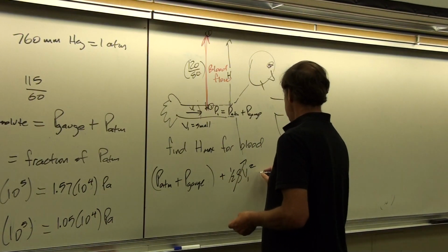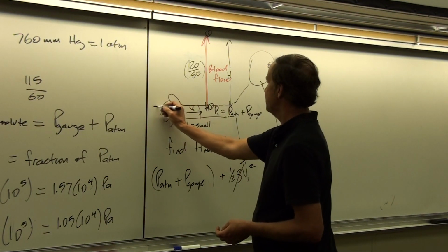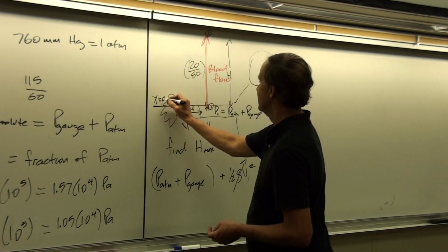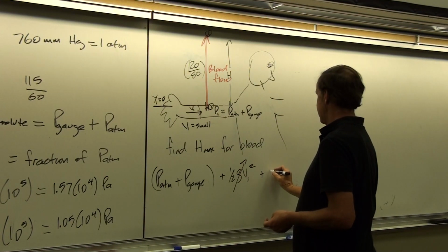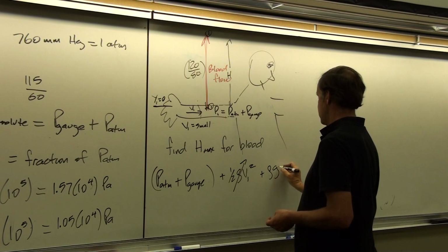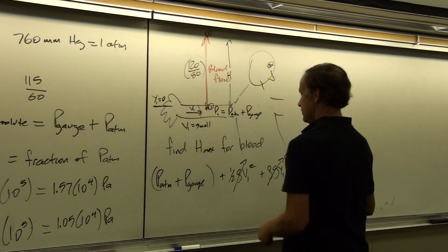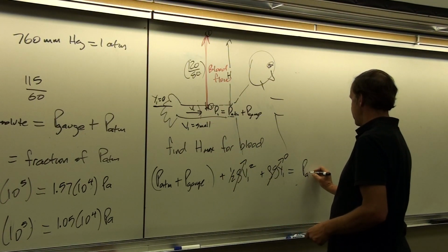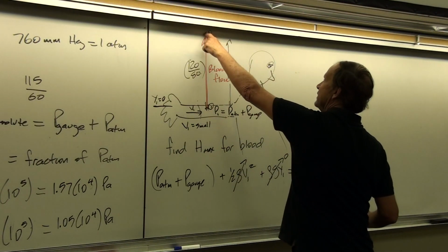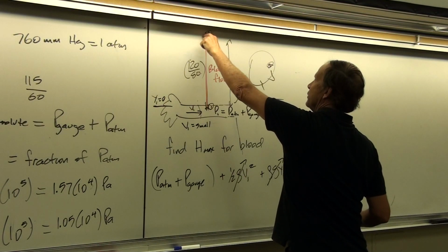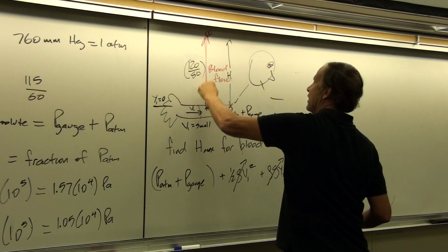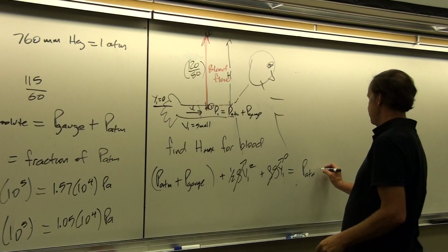And then here, because we'll call this point here y1 equals 0, we can neglect that term too. So this is rho g y1, that's also 0. And then here at point 2, we're going to have P atmosphere as the internal pressure of the air per unit volume at the top of this fluid column.